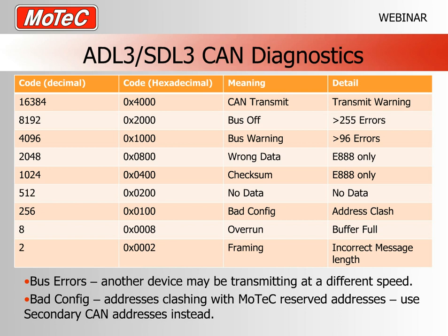So you'll actually use another set of CAN addresses, and this is often in the region of 200 hexadecimal. If you have, for example, some Ducati dashboard systems, they use some of the addresses in this same area for their dash communications from the standard ECU to the standard dash, and this would come again with this sort of address clash.